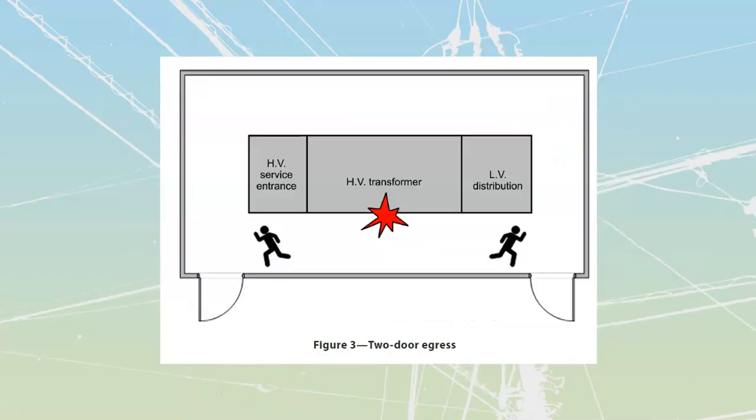Clearance requirements are going to be a big thing inside of our electrical working spaces. The CEC gives us the fact that we need to have at least 1 meter of clear space in front of any sort of electrical equipment. So in front of this electrical equipment, I need to have at least 1 meter of clear space. It should have secure footing, i.e. it shouldn't be uneven or be on a ladder or anything like that, just a level, flat area.